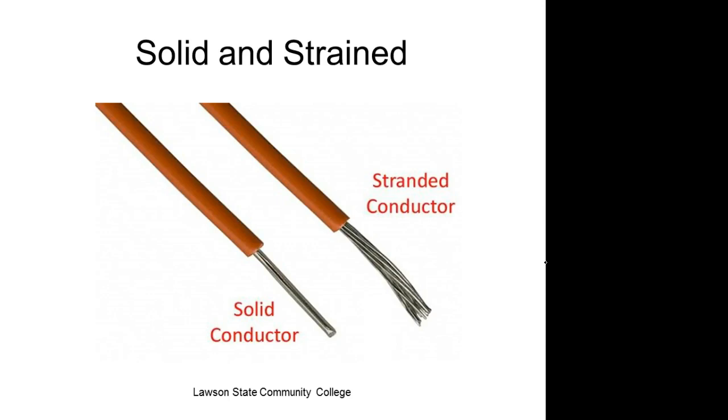The biggest problem we have with solid is that people don't know how to strip that stuff. Have you ever used what we call glass cutters? Do they cut glass? They scribe it. So the problem with solids is if you get a little nick inside them, you create what we call a scribe. You'll see people strip this solid strand wire with their knife, turn the blade directly in there, spin the wire around, and put a little loop right there. This wire is going to break.